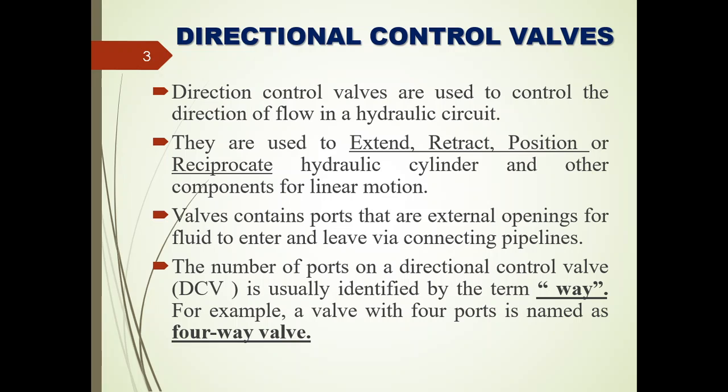The direction control valves are used to control the direction of the fluid flow, in which direction I want the fluid to move. The direction of the fluid controls the extension of the cylinder or the actuator, the retraction, the positioning as well as the reciprocation.